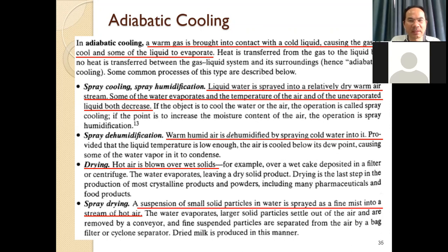Spray cooling means liquid water is sprayed into a dry warm air stream, and then some of the water evaporates. When some of the water evaporates, the temperature of the air and of the unevaporated liquid will decrease.